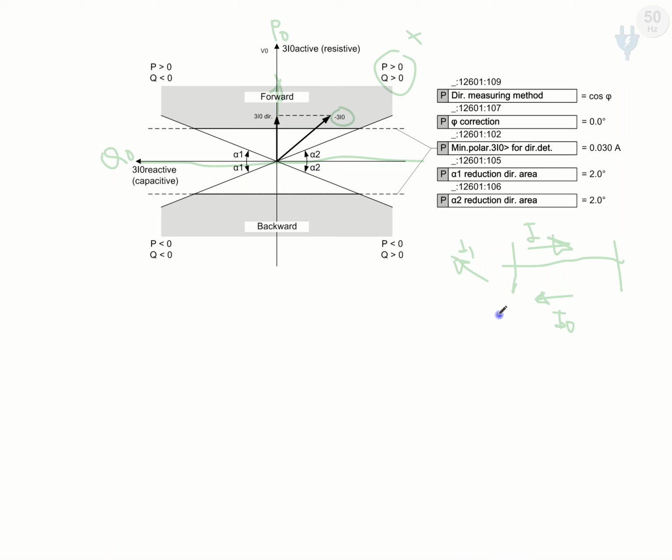This I0 is in the reverse direction during the fault. So actually this current is in this direction. The relay will understand this as zero sequence current. This is the current which this CT detects actually, but the case is that we should give a minus, so the direction becomes reverse, and the relay can understand it as lagging.